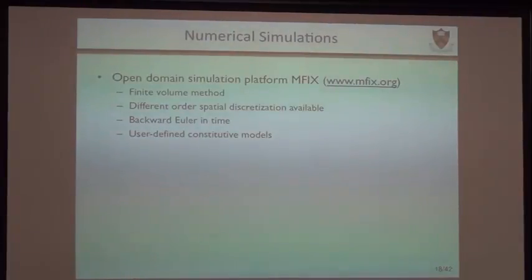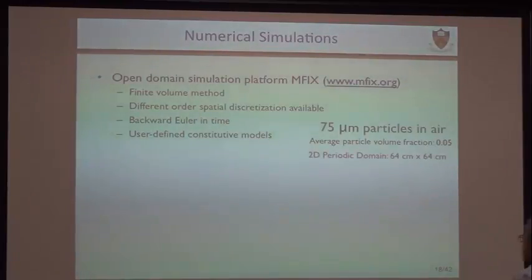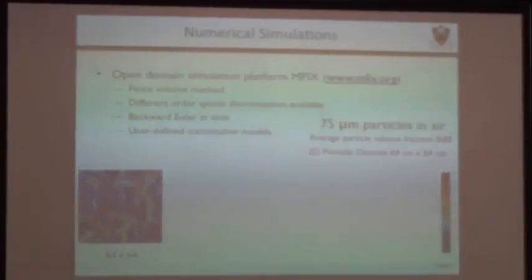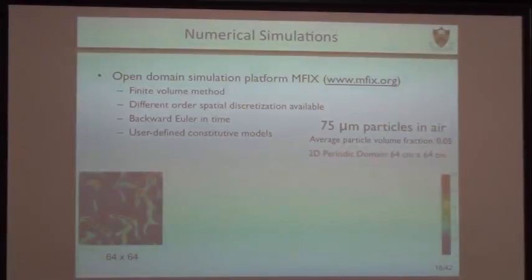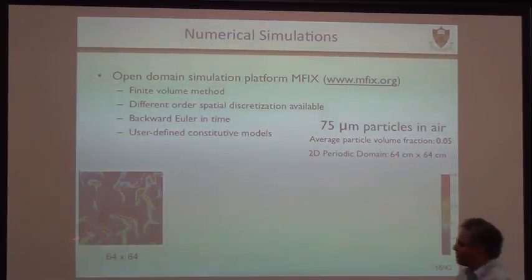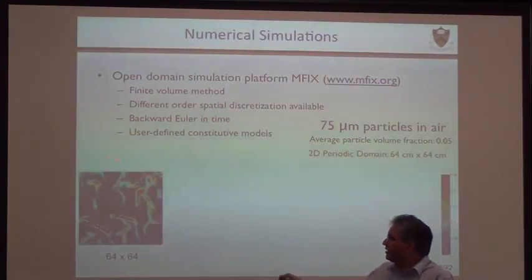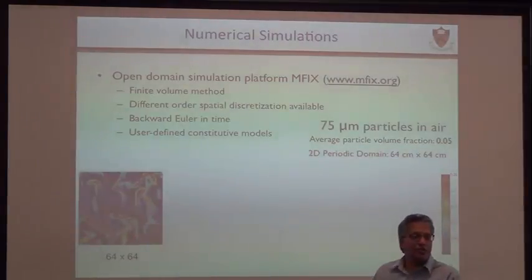So if you now say, okay, we have the model, it has all the right features, why don't I just simulate the whole thing? This is where the problem comes. We use an open source platform that has been developed over the years, and I'll show you some simulation. Here, we are doing a simulation in a fairly large region. To keep the wall effects away, we do a periodic domain simulation, about 64 centimeters by 64 centimeters. We put lots of grids, and then we apply a pressure drop. So we start with a homogeneous suspension of particles and see what these equations predict.